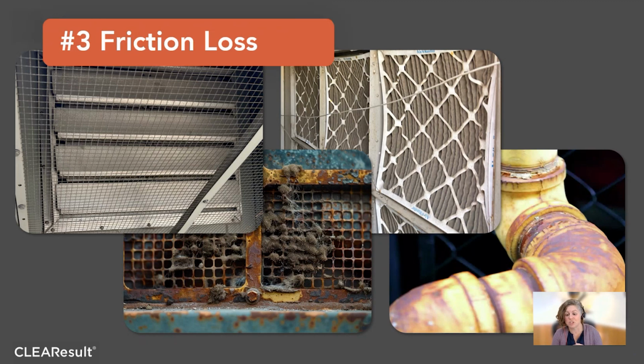Another good example of friction loss is this pipe that you see with lots of elbows in it. Anytime you're moving water or steam or whatever it is through that pipe, and you change the direction, you're introducing friction into that system, and you're losing flow, and you're losing energy in the process.